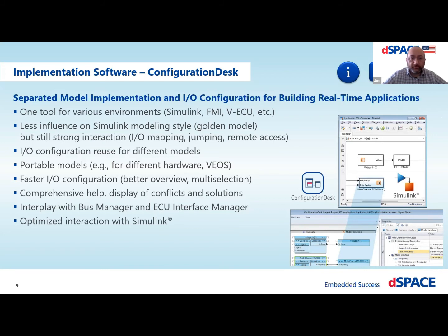We also have a tool called the Bus Manager that lets you import vehicle networks like CAN, LIN, and ARXML onto the system. And so in either case, whether you use RTI or Configuration Desk, the result is the same. You get an executable that can be flashed onto your dSPACE system that will run your control algorithms that you've written in Simulink.